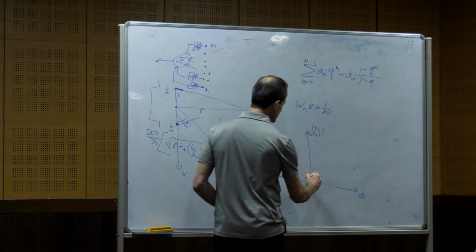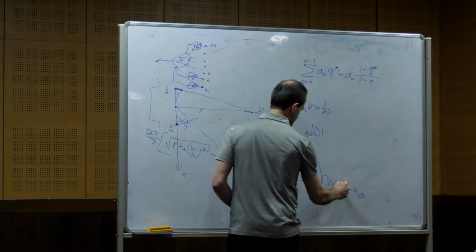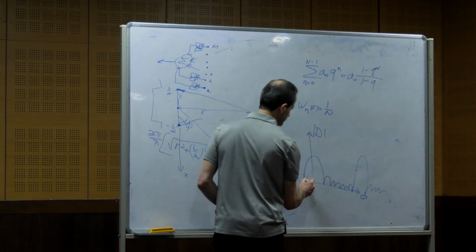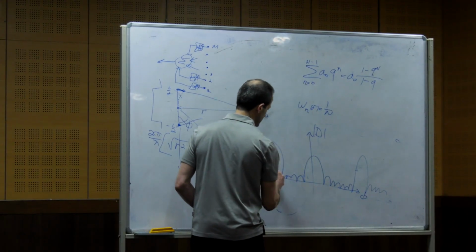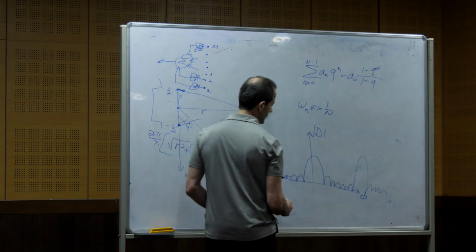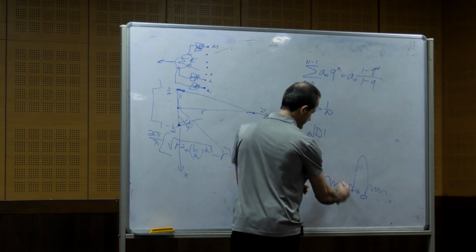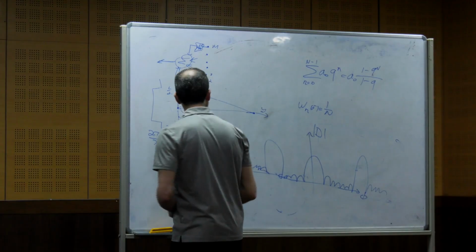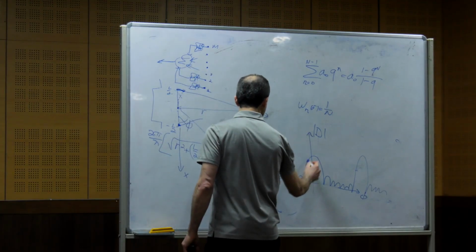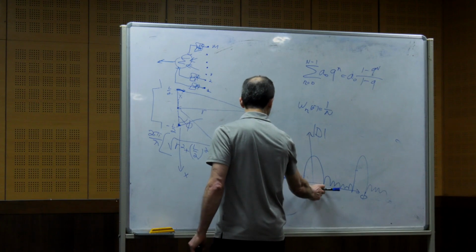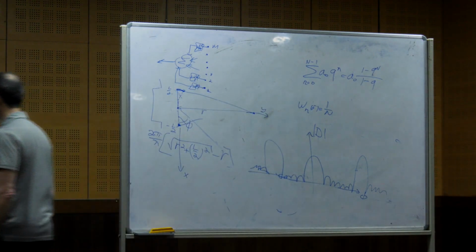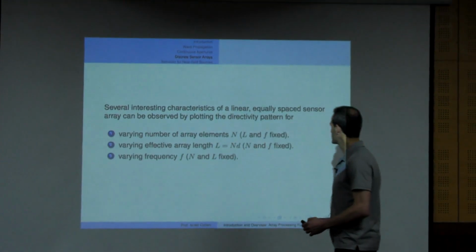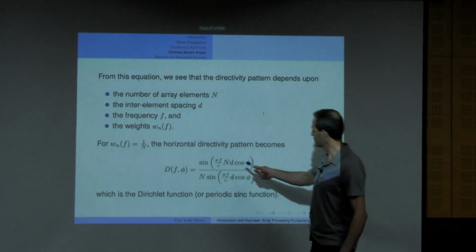So it looks like this. It depends on the range, it doesn't have to be like this, I will talk about it. This is periodic. We want to see the level of the side lobes and also the beam width, the width of the main beam. So if we change n in this function,